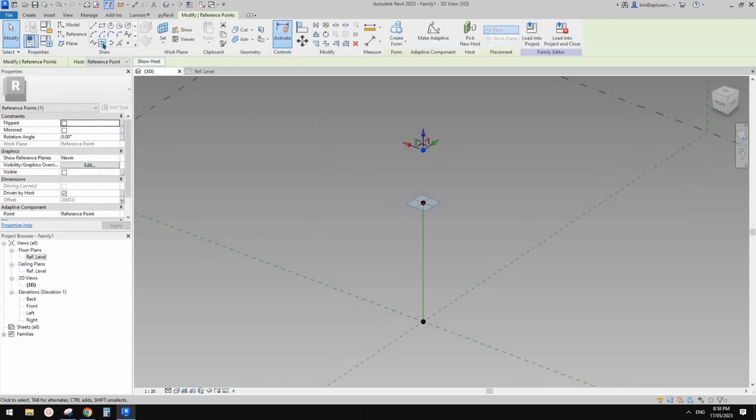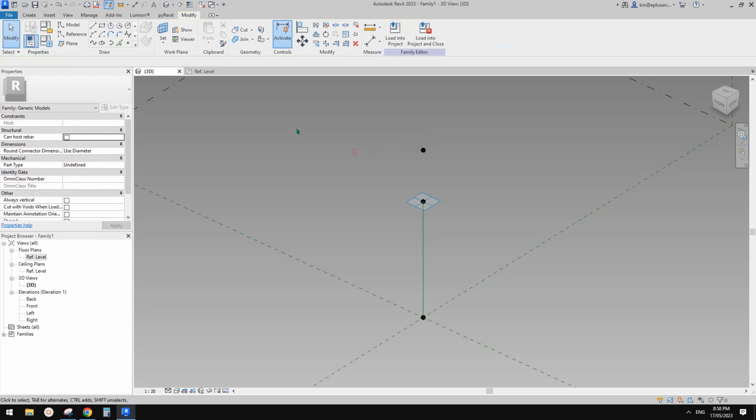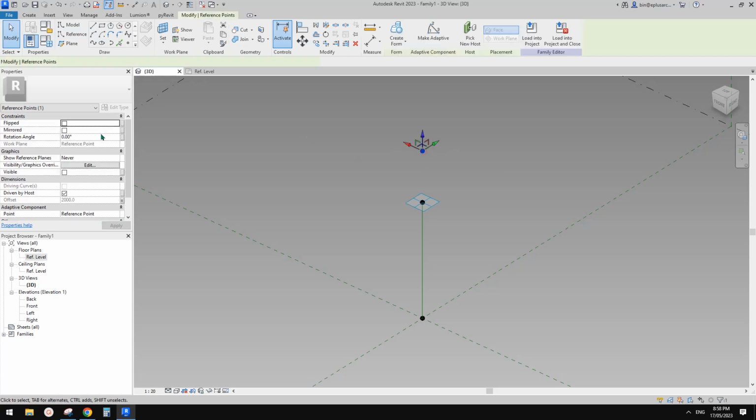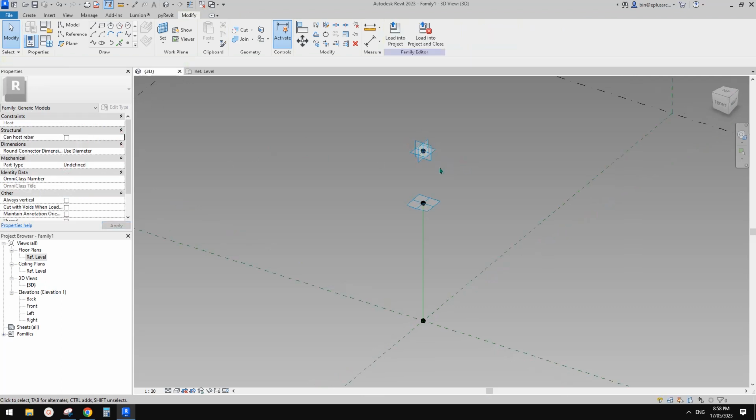So I'm trying to find a faster method. So you can offset a point from this point. Okay, so offset. Let me just turn on the reference planes so you can see all these. So you can place 2 points on one of the vertical work planes and then offset on each side, and you can then place another 2 points on the other vertical reference plane. So and then also on each side. But we can also do this.